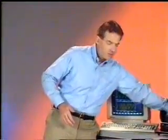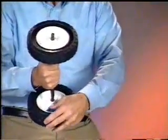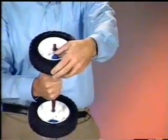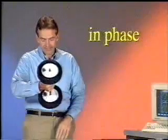Phase can be defined as the relationship between two events and is usually measured in degrees. For example, let's use this shaft with a wheel fastened to each end and add an unbalanced weight to each wheel in line with each other. As we spin the shaft, the unbalanced weights on the wheels pull both ends of the shaft in the same direction. So both ends of the shaft are said to be moving in phase with each other.